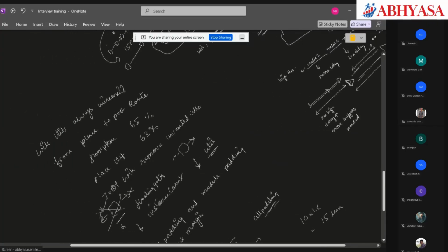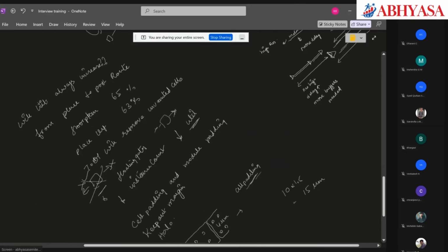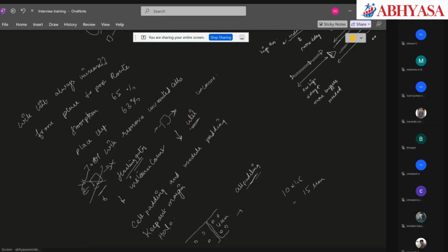and these are floating gates and unconnected logic, basically. Unconnected logic or floating gates. So many flops will be removed. If you look at your log file, the place log file and all, it will show you deleted these many flops. Deleted 100 flops because they are not connected. Deleted 30 flops because they are not connected. So this deletion of logic will cause your utilization to drop down.